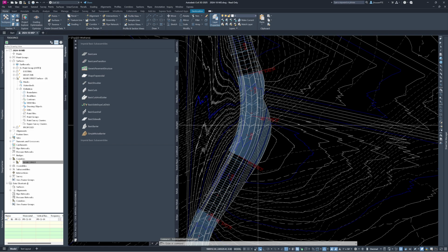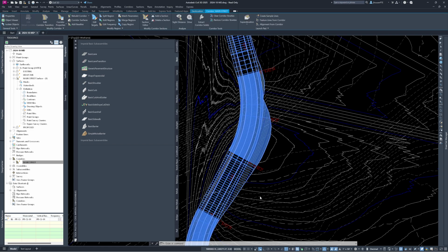So now we just have to go back in there and do that again. If you only want the corridor surface information, you can click on the corridor surface. It's the same tabs as what's in the corridor properties. So I don't know why they separated it out like that, but it is. Here's where it gets really strange, because right now there's no daylight shown as an option.